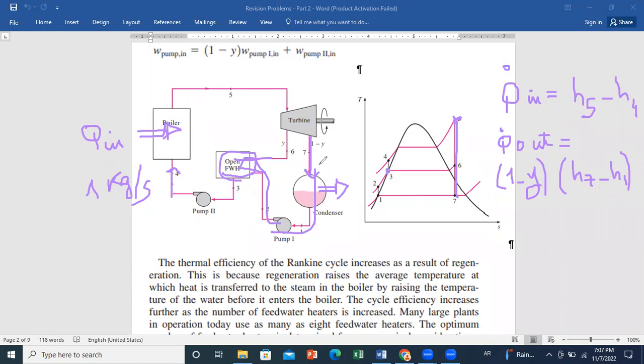The one coming from the pump will gain heat, the other will lose heat, and the heat lost is equal to the heat gained by the two parts of your divided flow rate. So this is an internal exchange of heat, not an exchange with the outer environment. This is why you don't include it in the efficiency calculation.